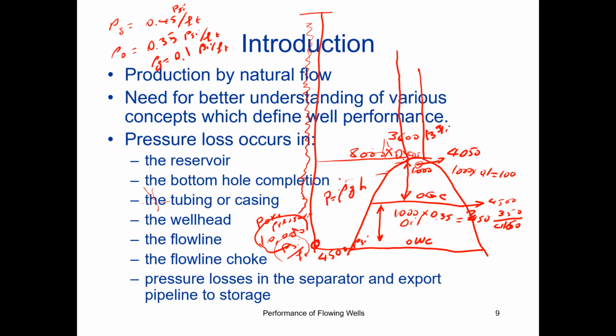13 3/8. Because otherwise, if you go with the same mud, you would have blowout. If you increase the mud weight to prevent the blowout, you might have fracture, deformation above cap. That's why intermediate casing, we need to put it on top of reservoir.